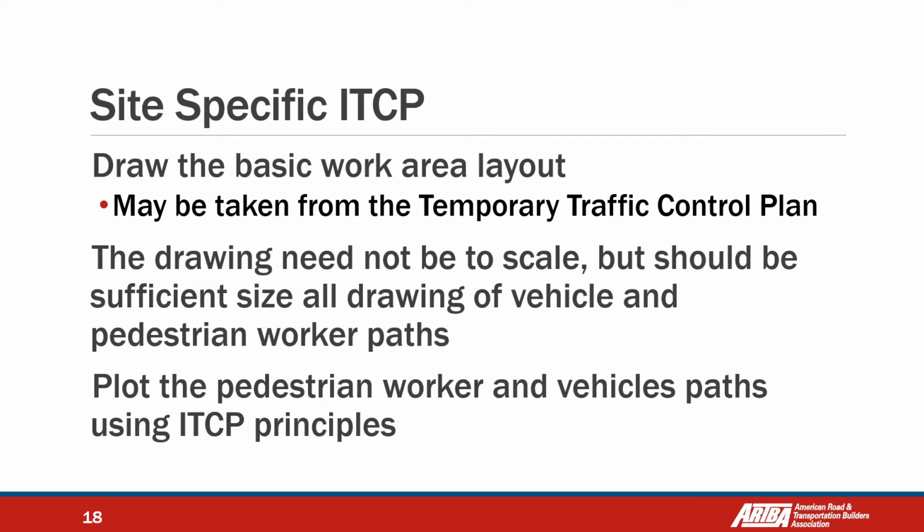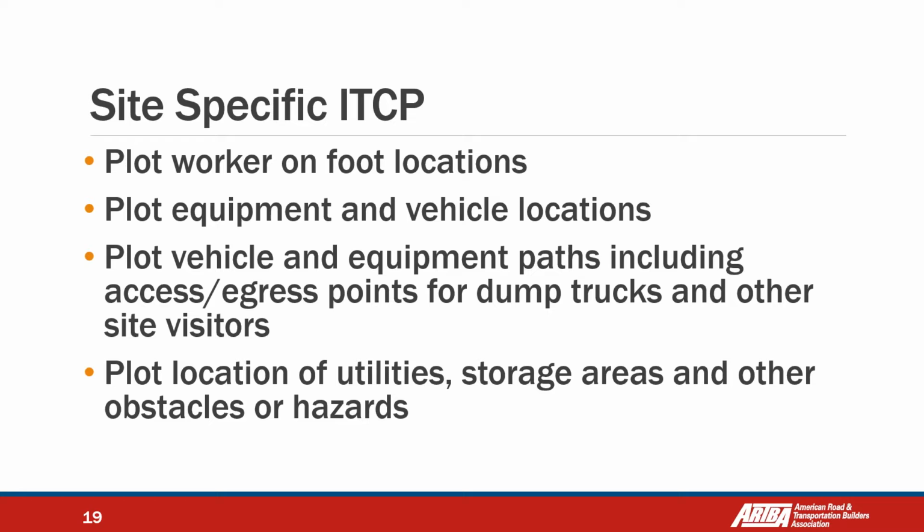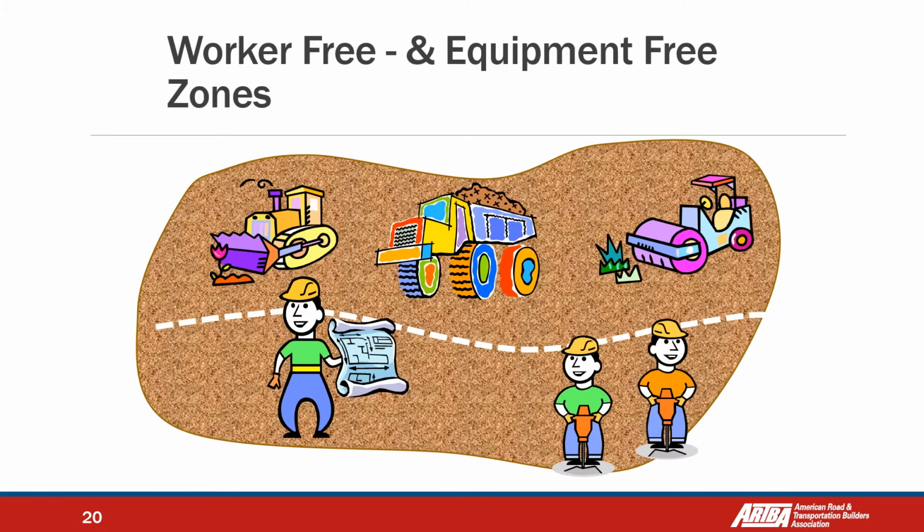Okay, basically separating workers on foot from heavy equipment. Plot workers on foot location, plot equipment and vehicle location, plot vehicle and equipment paths, including access and egress points for trucks and other site visitors, plot location of utilities, storage areas, and other obstacles or hazards.